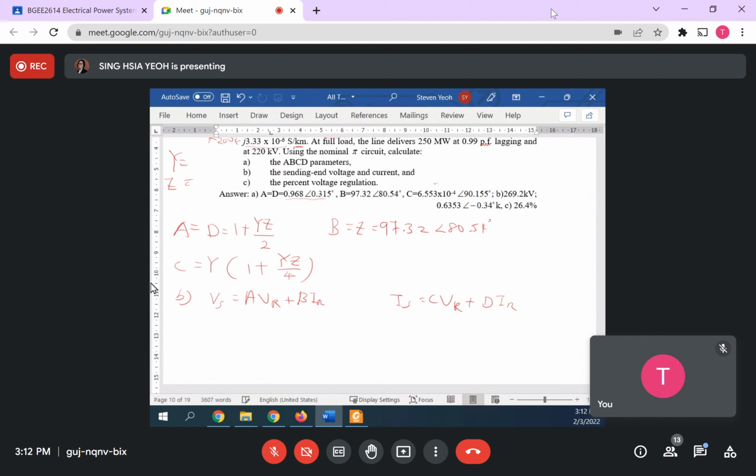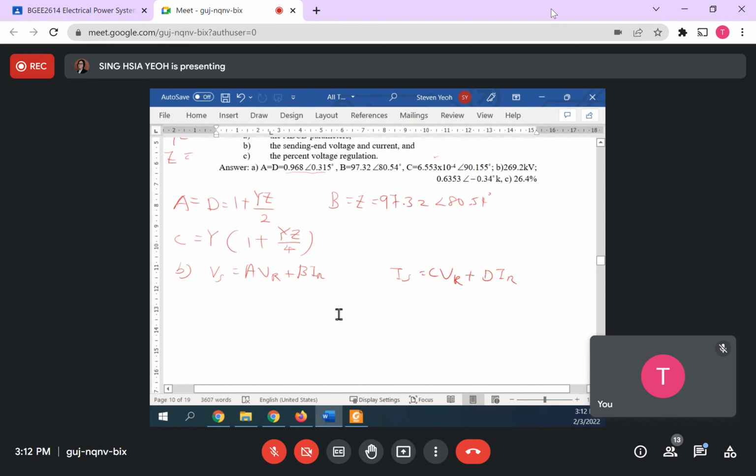So you already have the A, B, C, and D values, right? A, B, C, D here are okay already, right? Then what you need to find out is VR and IR. If you have VR and IR, substitute here, then you can get VS and IS. Okay. So what is your VR? I think I know what happened already. You all used line to... It's about line to line or line to neutral, maybe.